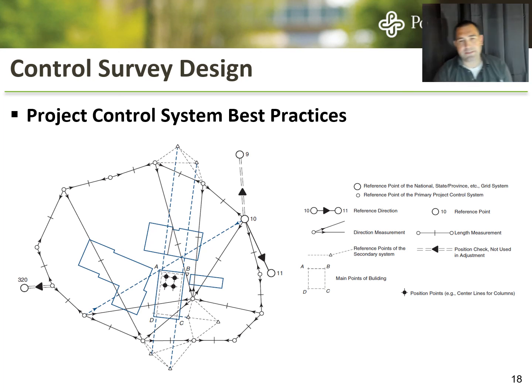All right, so the last thing that I want to talk about in terms of control survey, we just got done talking about the reference systems and grid coordinate systems. Your book does a little bit of discussion about project control. So if you were tasked, working on a survey crew, with setting up the surveying to lay out staking for a project, like where grading is going to happen, set up your system so that you could measure, is this building going up perfectly vertically? Maybe you even have temporary structures that you need to be able to identify the elevations of.